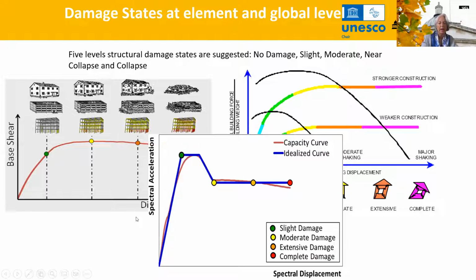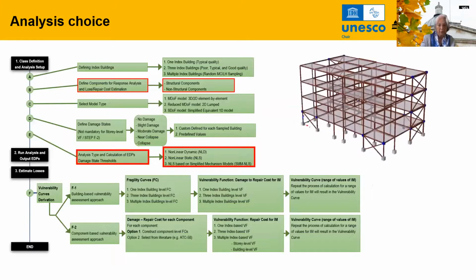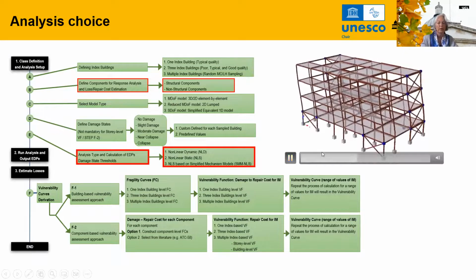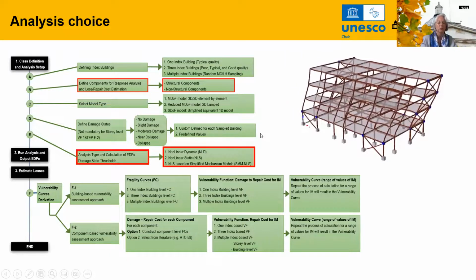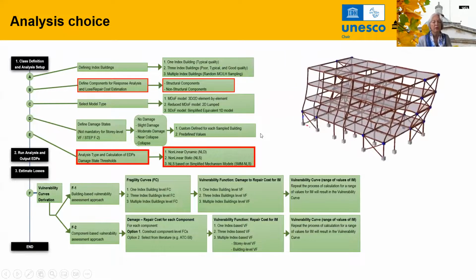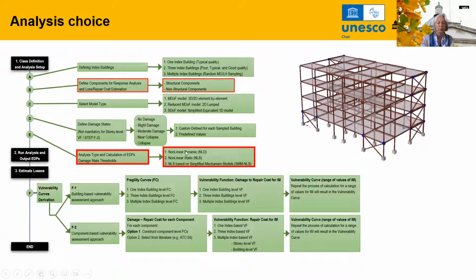And that then allows us to determine the performance of the building in relation to the type of analysis that we can run. The type of analysis, again, can be different. We can go from a nonlinear dynamic analysis to a nonlinear static pushover analysis, which is what we will concentrate on this afternoon, to very simplified mechanisms models, or just more simplified pushover analysis.